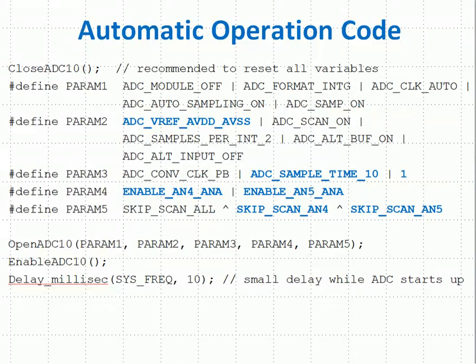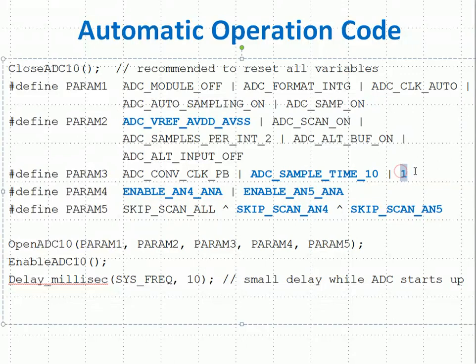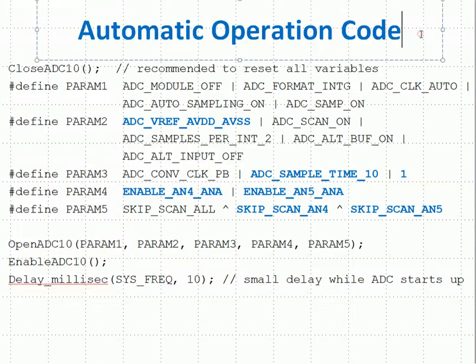Automatic mode is similar. We could change the reference voltages if we want. We can change the sample and hold sampling time. We can change that TAD parameter that I called X before.